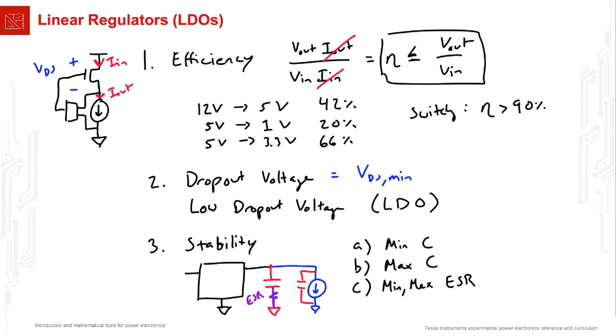If you have too much ESR, then the capacitor doesn't really look like a capacitor anymore, it looks like a resistor. But the minimum ESR can actually throw people for a loop sometimes, and in fact I've fallen for this myself. Some linear regulators' control loops are actually stabilized by assuming a certain amount of ESR and taking advantage of the zero associated in that control loop.